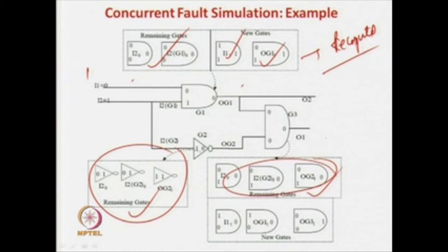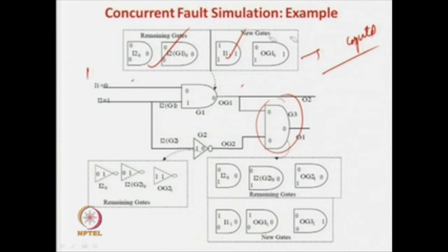Similarly, for this gate if you check, some new gates will be added. So, what is the new gate that is added? Now obviously you can see that this was a stuck at 1 fault here, this is actually 1, this stuck at 1 fault over here. So, if we stuck at 1 fault, then the answer is a 1 over here. So, there will be a signal change here. So, this gate will be added by this one. So, stuck at 1 here means the answer is a 1 over here. So, instead of 0 the answer will be 1 1 1 0. So, this stuck at 1 fault is a new fault which is added, which gets retained over here.